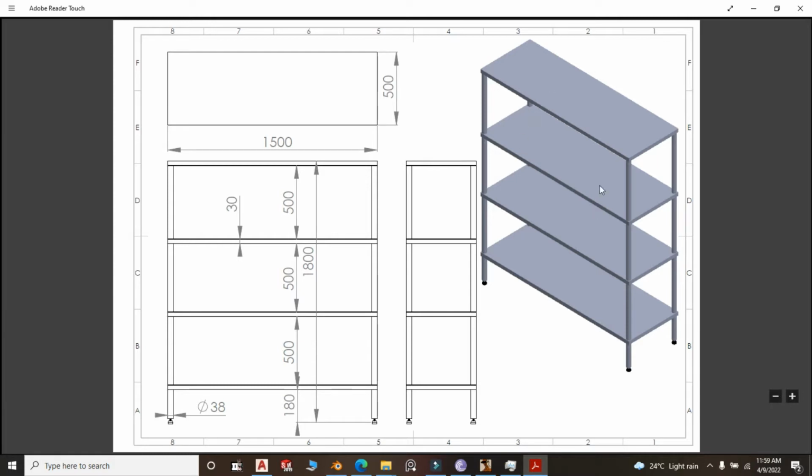The design is very simple. We are going to design the top shelf and the mid shelf, and the others you just duplicate from the mid shelf. The difference between the top shelf and the other shelves being that, as you can see, there is a hole where the leg will be going through in the 3 shelves, but on the top one it is solid because you don't want the leg protruding on the top there.